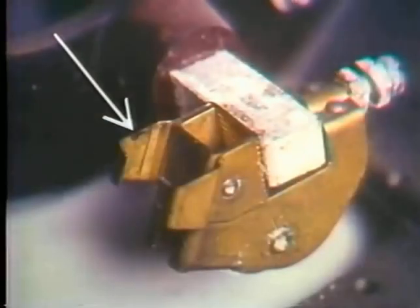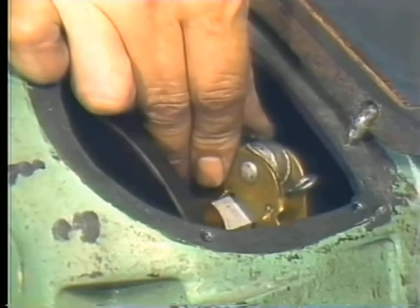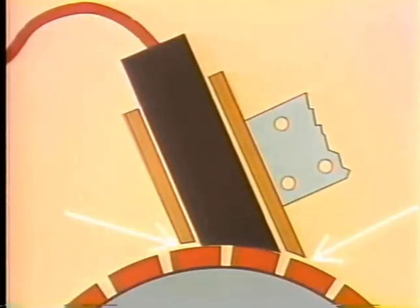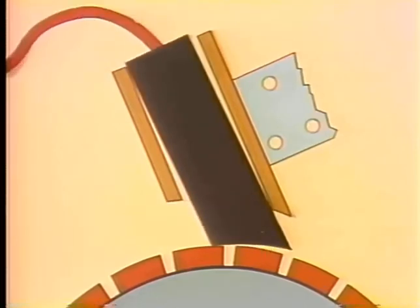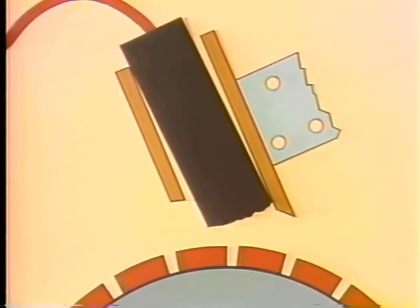These bottom edges should be smooth, straight, and free of burns. Now, most brush holders can be moved, so making sure they're properly adjusted is essential. What you adjust is the amount of distance between the bottom of the holder and the surface of the commutator. Always check to see that the space between them is correct. If the rigging's too high, the brushes will chatter and make a hissing sound, or the brush could lock in the holder and break contact with the commutator. The brush could also get hung up and break off.